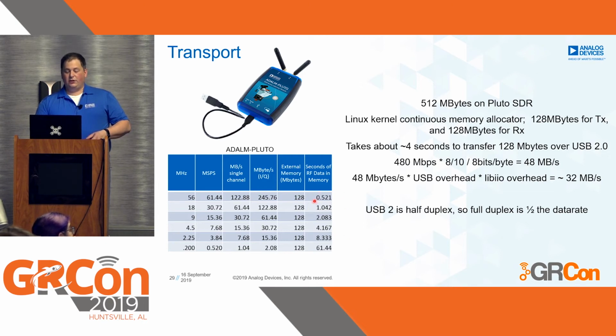But you can still store half a second of information at 61.44 and then slowly stream that out of the device after you've captured it. And a lot of people will do that to capture a signal and then analyze it later, for signals intelligence or just for algorithm development.